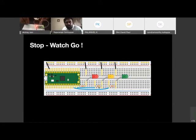So if you look at the second one, you have put the resistor here, but this end of the resistor is connected to this output port of the Pico board using this jumper cable. Same way, this resistor is connected to this port of the Pico board using this jumper cable. The other end of the resistor is connecting to the diode, to the LED. And then the LED is getting grounded. So the circuit is getting completed through the Raspberry Pi, right?